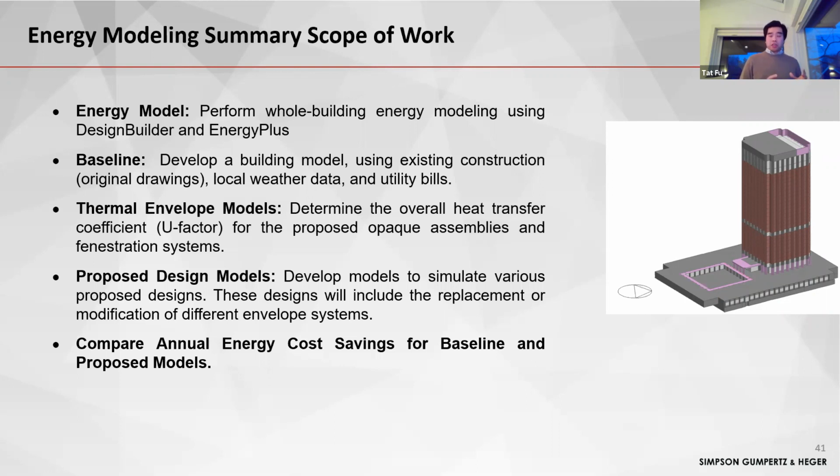We also have the envelope model that has run through the options, cases 1, 2, and 3, and the R-values related to that. Then we incorporate those different envelope renovation options into our proposed design model, and we'll compare the energy cost for the baseline and the proposed model. Next slide, please.